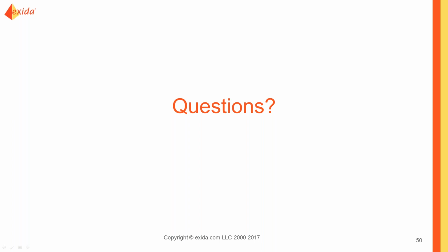How do you determine how often proof tests should be performed for various devices? There are going to be 3 things. One is there's going to be a plant operational philosophy that we do tests once a year, once every 6 months, or say, once every 3 to 5 years. So there's going to be a plant desire for the frequency. There's also going to be a requirement that that proof test is run at least twice as often as the